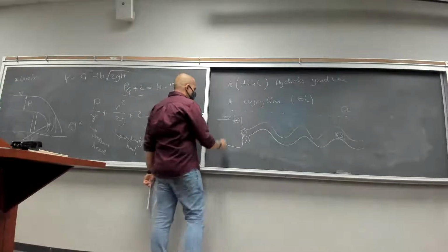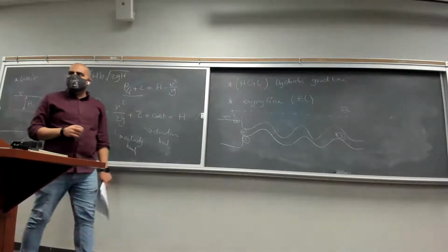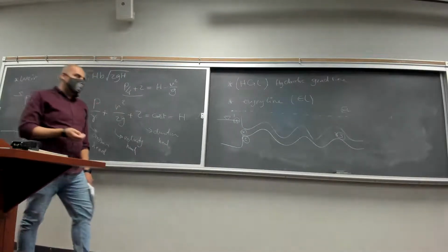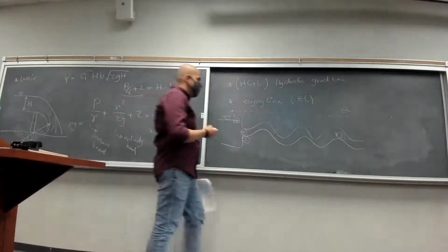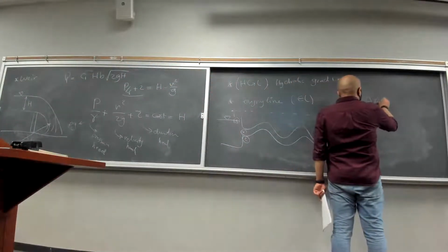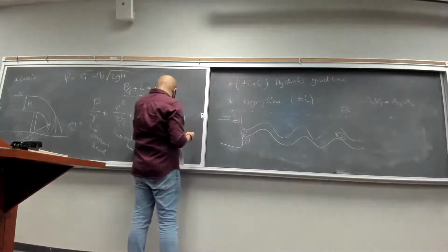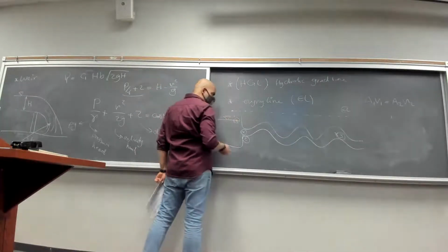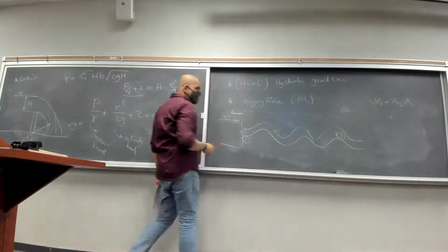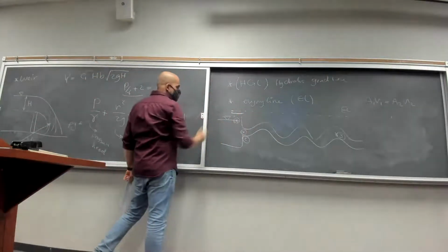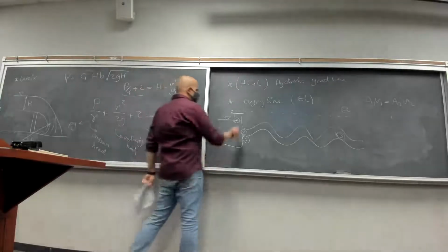So do we have any change in velocity between here and here? Between the free surface and the entrance of this pipe? Yes, right? How can we determine that? Continuity, right? A1V1 is equal to A2V2. So your hydraulic grade line starts here. We don't have any other color. It starts here, and since your velocity is increasing, because area is becoming smaller and smaller, your total hydraulic grade line is going to drop, right? So we'll see a drop.